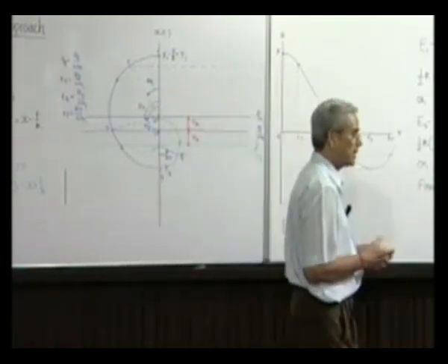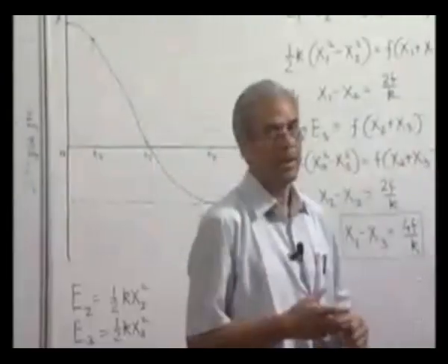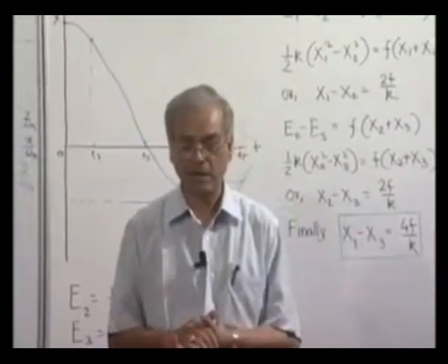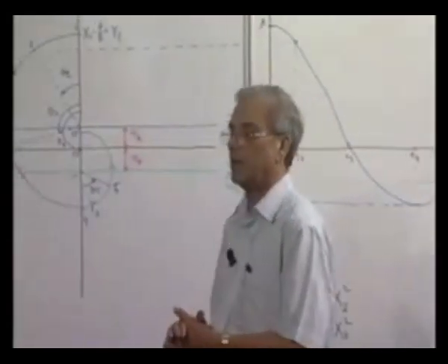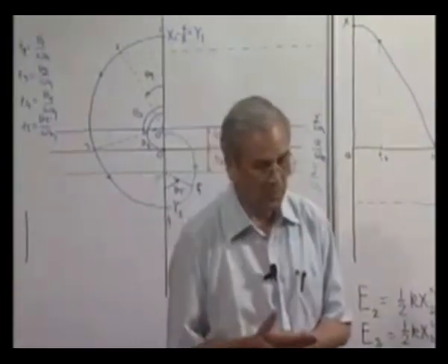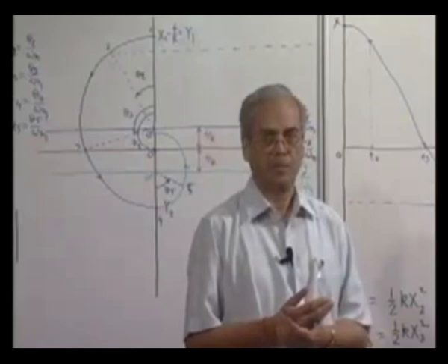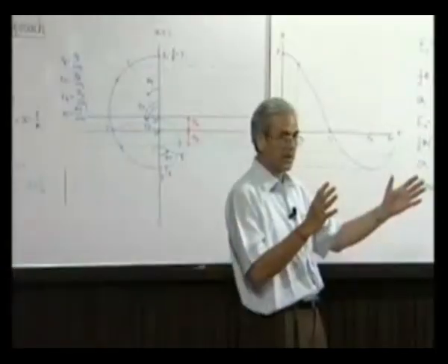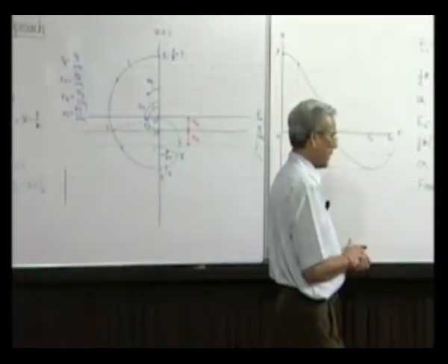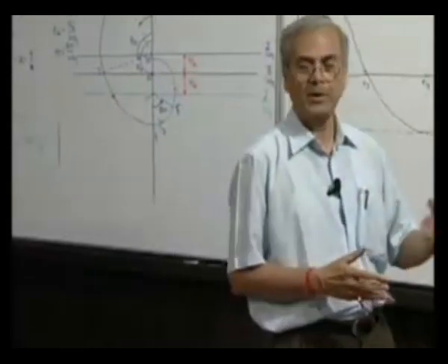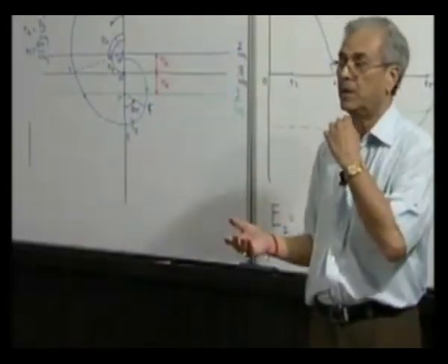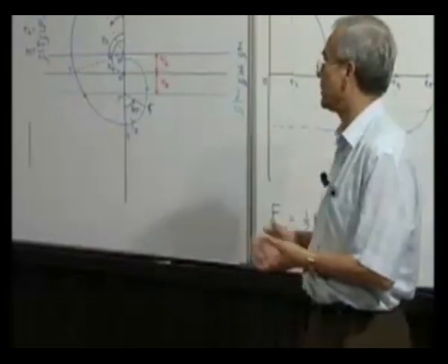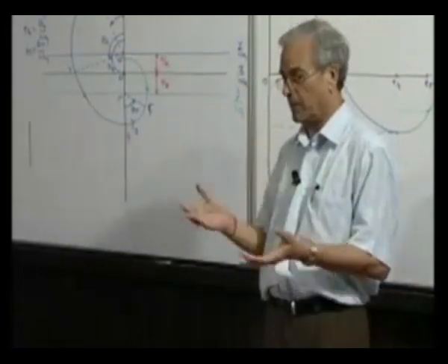We have seen in viscously damped system, the time period is slightly increased because the damped natural frequency is slightly less than the natural frequency of the same system without the damper. And in case of Coulomb damping, we have seen that the natural frequency or the time period remains the same as the undamped system.